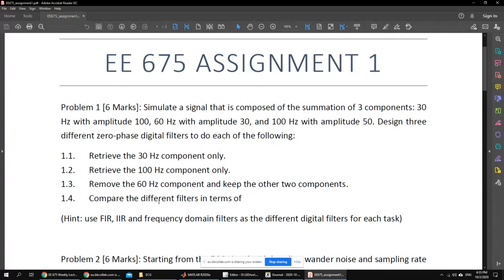Did you use the right specifications for the filter? Yeah, I did it in the filter designer and then copied the code. So it works with filter? If I just use filter, then it works. The IIR works, but if I change to filtfilt, the result becomes zero. It's kind of strange, but you might want to change the design of the filter.